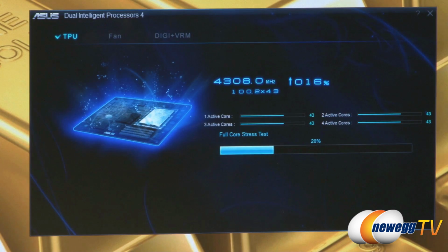But one of the changes that you're going to see as part of the automated auto-tuning process is that we now have per core tuning. So before we used to dynamically raise all the cores, but in this generation we're actually taking advantage of something that's already been available in our UEFI or in our software, which is giving you the ability to do independent adjustments for different threads. So if we want to go ahead and have 2 cores for single thread and 2 thread applications be set like, let's say 47, and then 4 cores set at another set of frequency, we can go ahead and do that. So right now you can see right here that it's actually running a stress test. If you want to go ahead and maybe right click and open our task manager, or I can go ahead and launch it either which way.